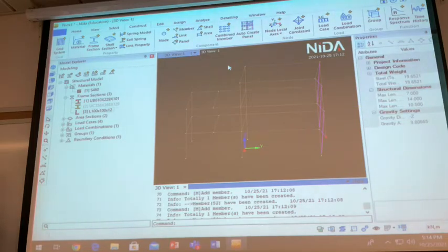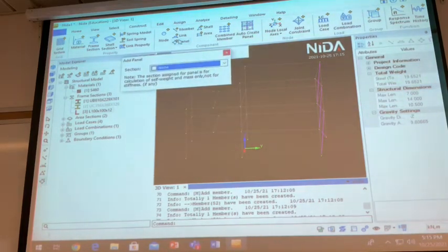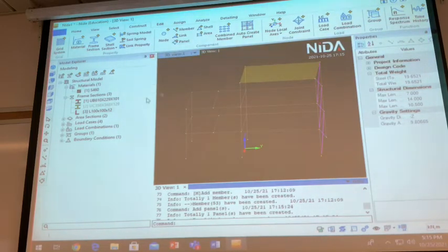Okay. So now you need to input the virtual slab. When you want to add the virtual slab, it's safe to add a beam element. You can go to the last one at your left hand side. Because I don't need to put any stiffness. This element doesn't have any stiffness. It just helps us to transfer the loading from the slab to the beam. So we don't need to define any material property for this. Okay, done. And then second.